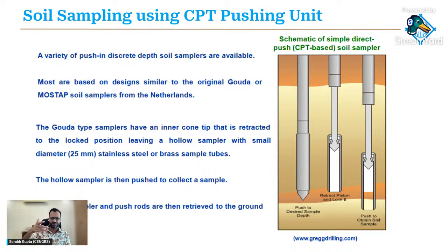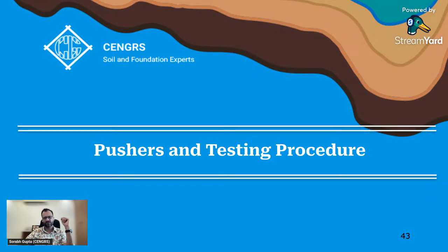Rather than arbitrarily collecting samples in all kinds of strata, we are trying to collect undisturbed samples in sand, in clay, and so forth. Here, you can look at where the clay layers are, go down to that layer exactly, pick up an undisturbed sample from the clay layer, and take it to the lab for testing. So that's with the cones and the CPT sampler.